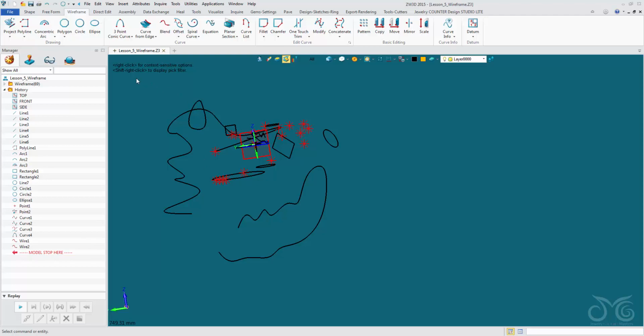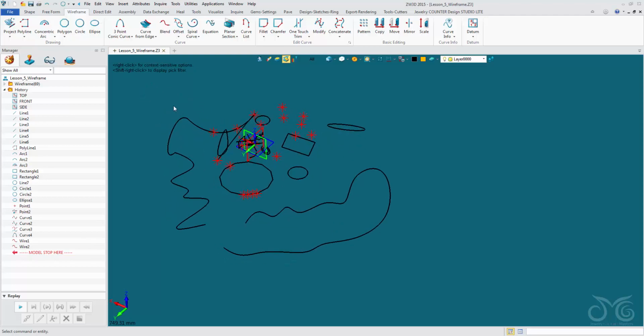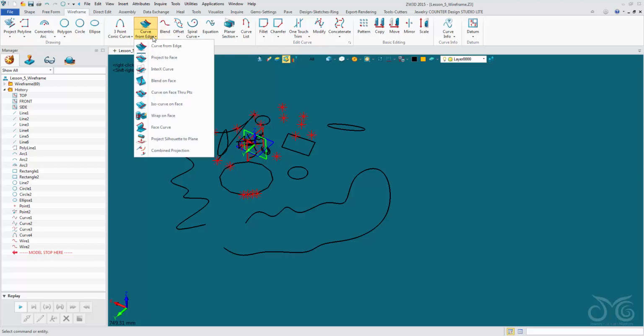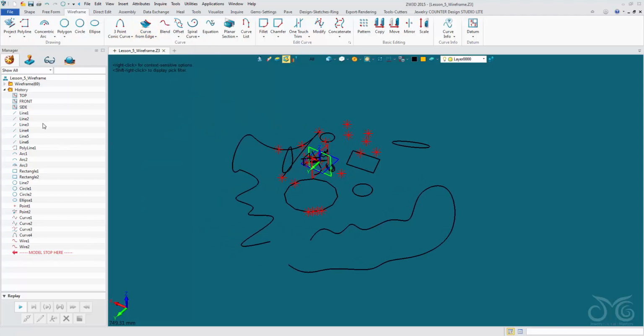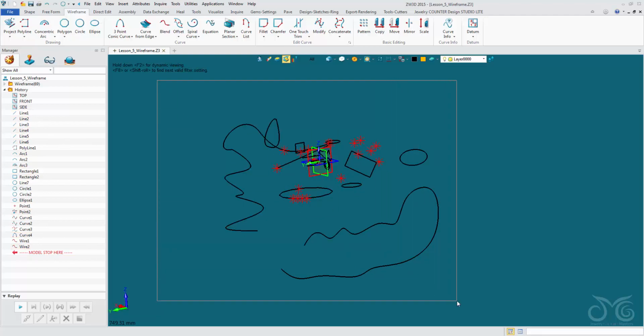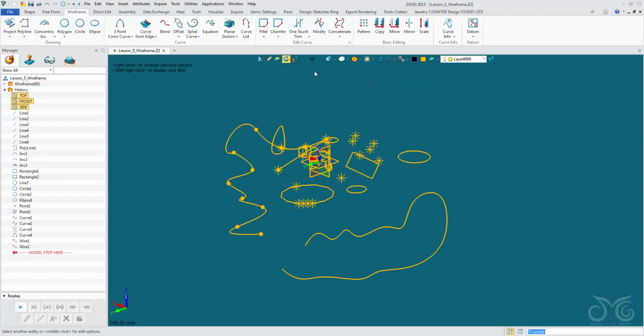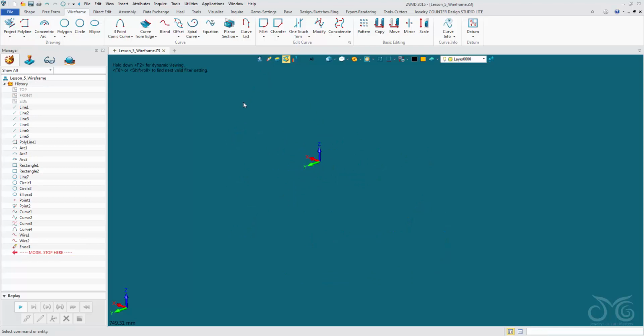So now I'm going to window pick everything, and I'm going to delete it so I can bring in a few entities that I can use to show you these commands. Okay, so I could delete the history. But this time I'm going to window pick my entire contents with my all entity filter. Okay, and then I can erase. Now you'll see that my center datums are also selected, so when I erase, they are gone too. Okay, I do not want to erase these, so I can undo this operation.